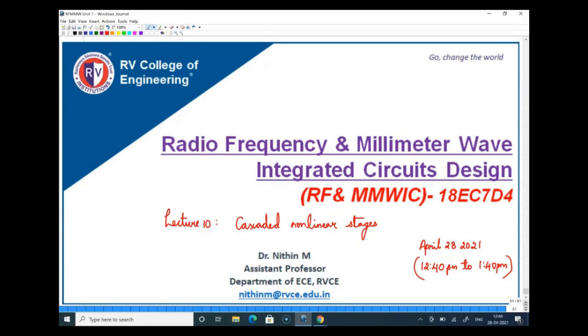Welcome to RF and millimeter wave IC design class. This is lecture number 10, and so far in the previous 9 lectures, if you remember, we started by talking about two different issues in RFIC, and we said that one is related to non-linearity and another one is related to noise. Both non-linearity and noise will be covered in Unit 1 itself. In the previous classes, we looked at the effect of nonlinearity in a little detail, and we observed the different nonlinear effects like harmonics, intermodulation, cross modulation, desensitization.